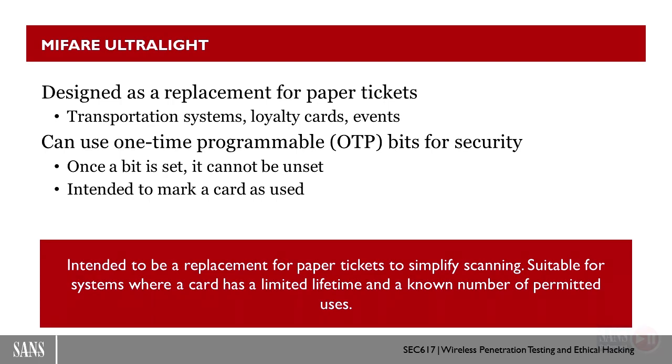So if we were to say use this for transport, and we have 5 rides on, say, the local transportation system, every time it is read, we could set an OTP bit to not be able to be updated anymore, and then we could effectively consume the card's stored value. So one card is good for one read, set the one-time programmable bit. Once you set it, it can't be undone.